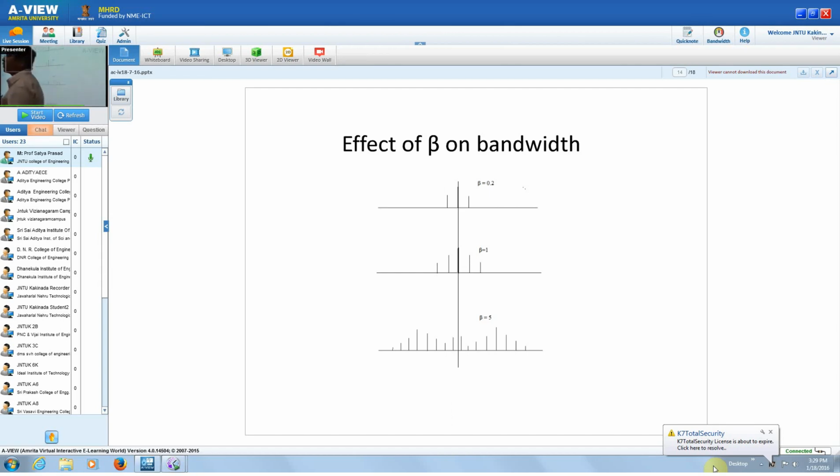Okay, M we said is equal to 1. Whereas here for beta we don't have any restriction. Beta depends on the relation between your frequency deviation and FM. So how much frequency deviation you want, and what is the baseband frequency that we are going to have.